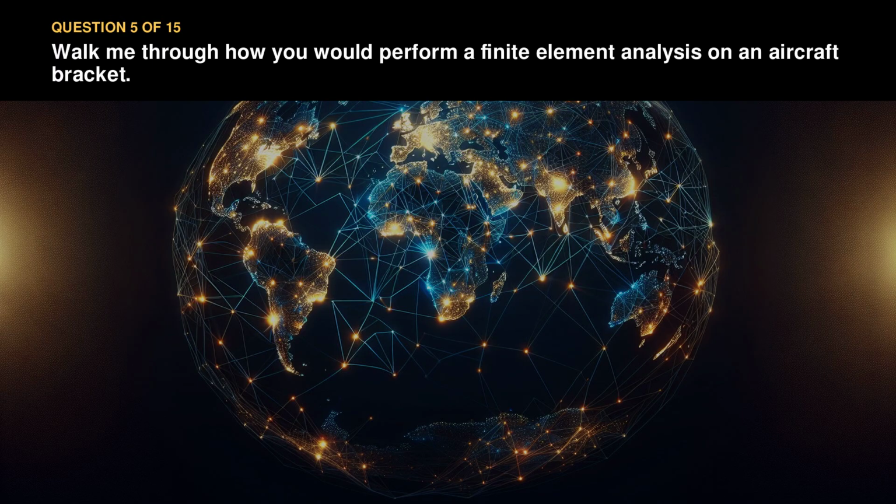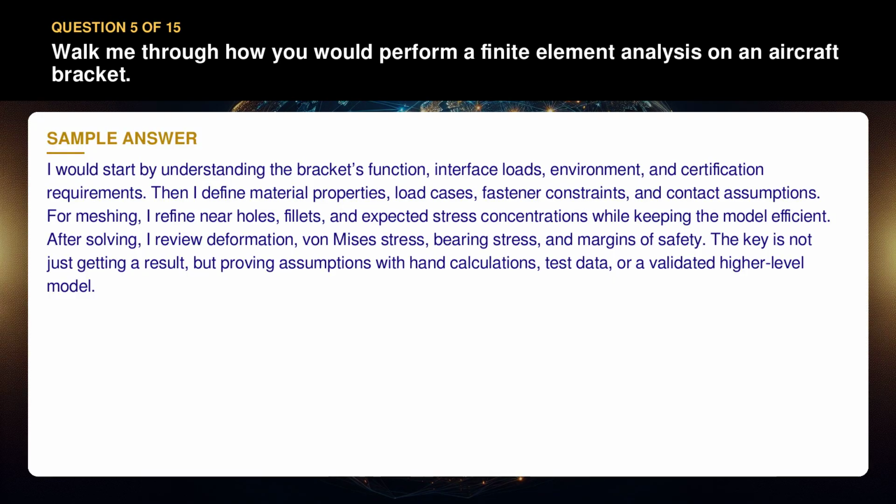Question 5. Walk me through how you would perform a finite element analysis on an aircraft bracket. I would start by understanding the bracket's function, interface loads, environment, and certification requirements. Then I define material properties, load cases, fastener constraints, and contact assumptions. For meshing, I refine near holes, fillets, and expected stress concentrations while keeping the model efficient. After solving, I review deformation, von Mises stress, bearing stress, and margins of safety.